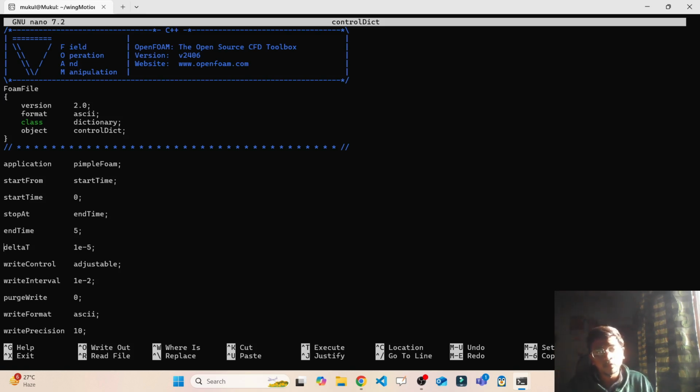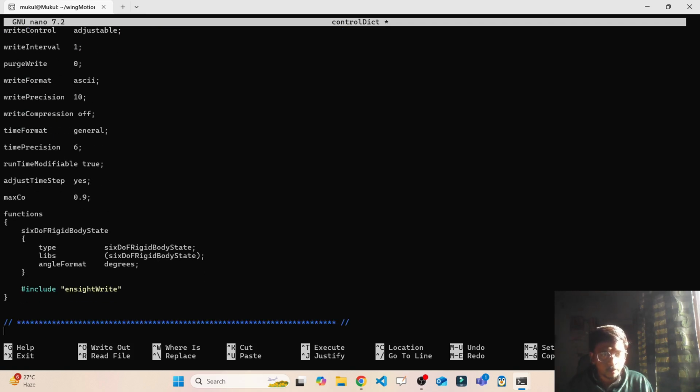Okay, so that will take much time, and I don't want that, so I will change it. I will make the end time 10, and I will make delta t 1, and for the write interval I will change it to 1. Okay, and everything else I will keep as it is.